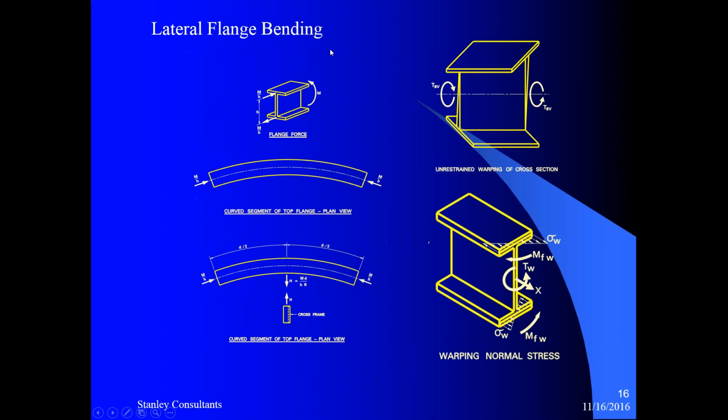So now what happens with the diaphragms in place? From the V-load equation, we can say that the diaphragm force will be M D over H R, and as we discussed in the previous slide, the top flange will be pushed inside and the bottom flange pushed outside in the positive moment region.